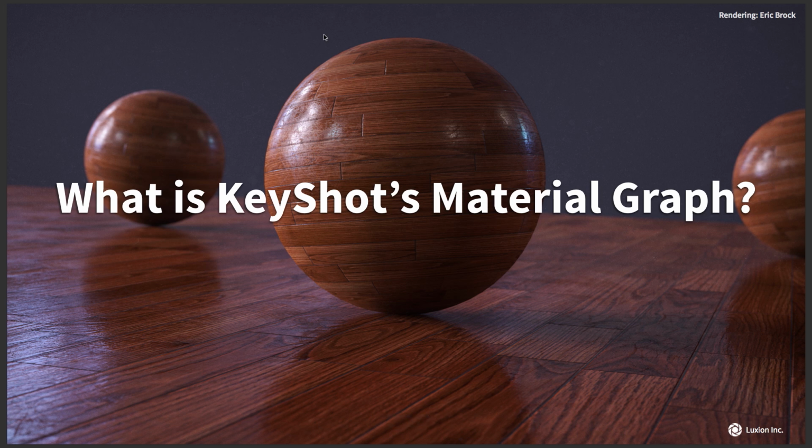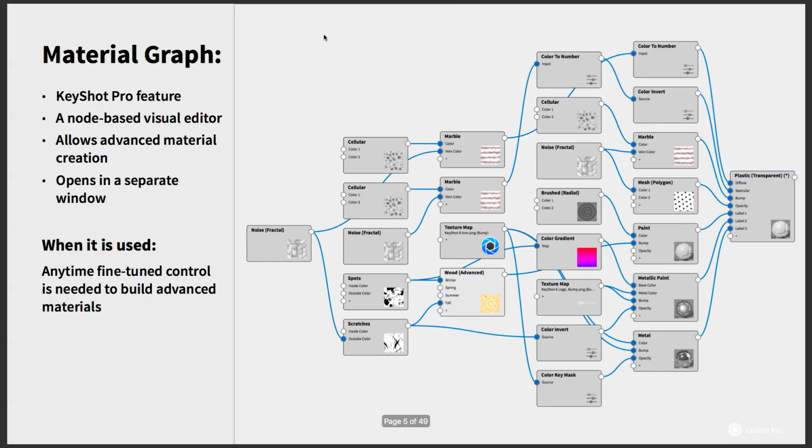Now, before we can start talking about how to use the material graph, we're going to want to know what the heck it is. Again, some of you may be completely new to it. KeyShot's material graph is a pro feature. It is a node-based visual editor, and when you open the material graph, it opens up in its own window. So it's a separate workspace that allows you to create advanced materials. Anytime you want to customize a material beyond what you can do in the material properties tab that you're used to working in, the material graph is a great way to do that.